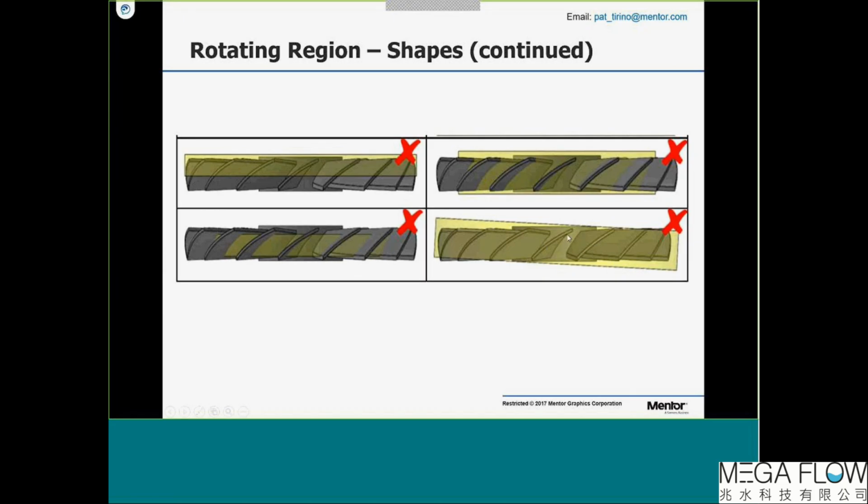If the fan itself is not aligned with respect to the global system, then it might be a good idea to rotate the model so that everything is aligned, or at least the fan may be. It just makes more sense if you can do that. If not, then just make sure the rotating part aligns itself with the fan part. Okay. Again, this just doesn't make sense. It may run, but I just can't imagine the results would make sense here.